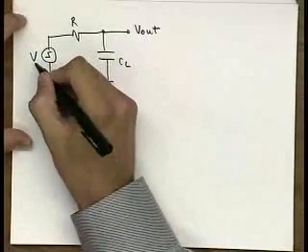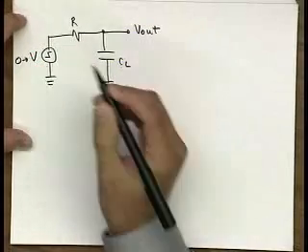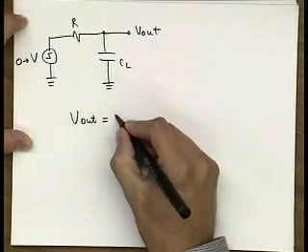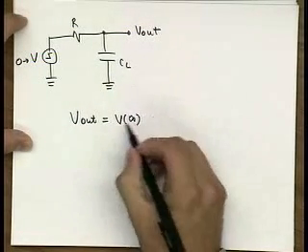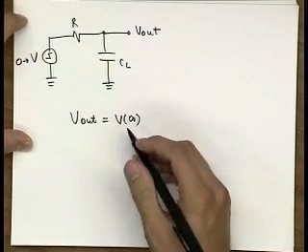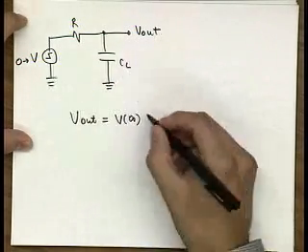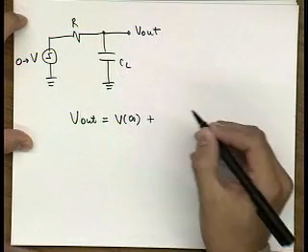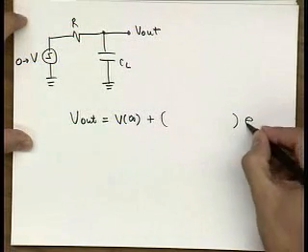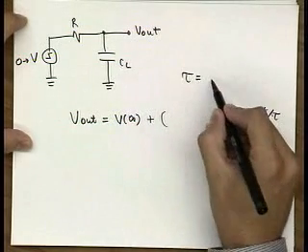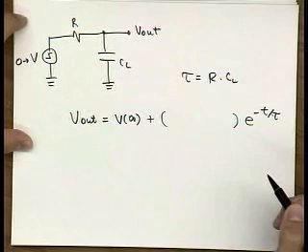So if you have this input waveform going from 0 to V, then you have simply that your output has to settle at value V in infinity, when you let an infinite amount of time after this step. And you also have this exponential term, e to the minus t over tau, where tau is this time constant defined by R and CL, C load.